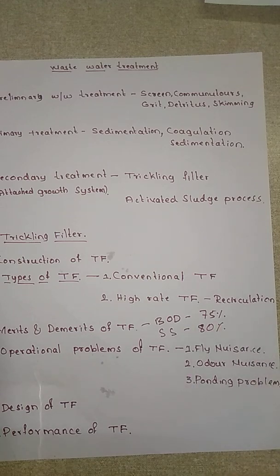Then odor nuisance: as decomposition of microbes or organic matter happens, the odor nuisance will be there. It is the odor of H2S gas. The usual remedy is to chlorinate. We can chlorinate the trickling filter, and we can prevent the formation of H2S gas.